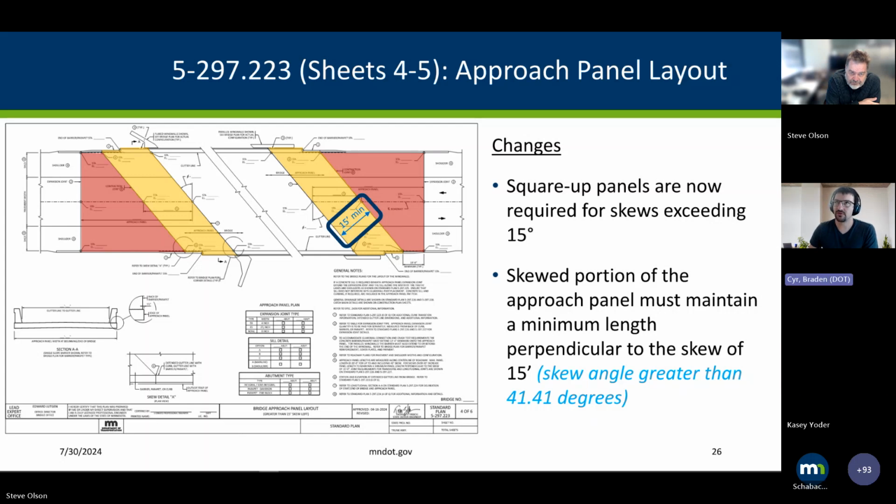The whole reason for that 40-foot limit for the smaller bars is that if you're picking them up in their smaller bundles, they tend to deflect a lot. If there's large bundles, I think the BDM allows you to go above it, but we decided on sticking with the 40-foot for the number 4 bars on approach panels, but not decks, because with decks you would be ordering a lot of them. Okay. All right, that's it.